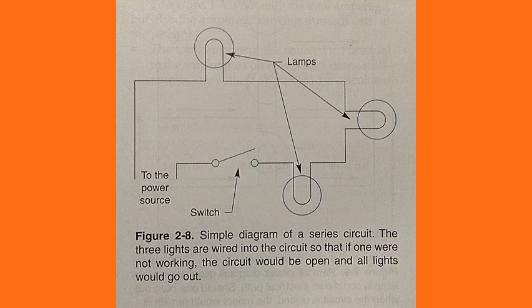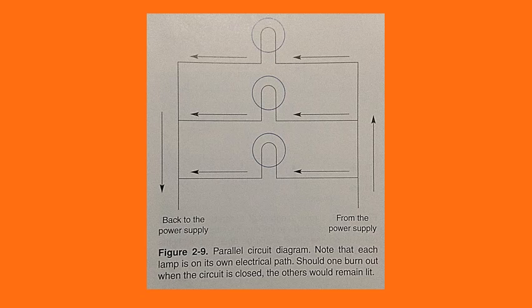A simple example will explain why. Older Christmas tree lights were often wired in series. Current had to pass through every light bulb for the string of lights to work. If one bulb burnt out, all the lights went out. Past the burnt out bulb, that is. Finding the defective bulb was a trial and error operation. Each bulb had to be removed and tested. Residential circuits are set up so that a malfunctioning or non-functioning load will not stop the electrical current in the remainder of the circuit.